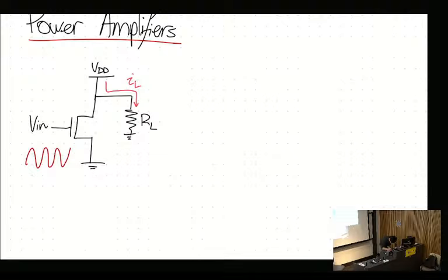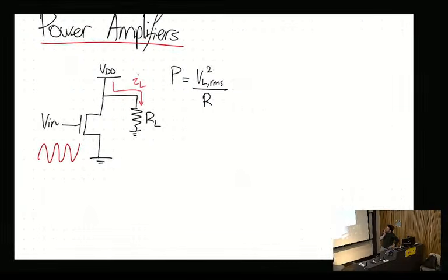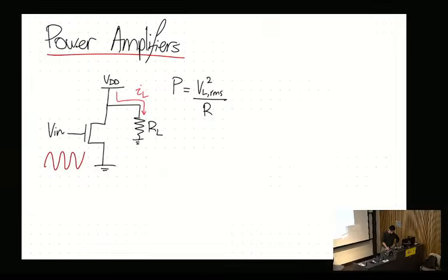And then the power at the amplifier is just V load RMS squared on R. So, just the standard power relation, V squared on R. Then there's the question of how we actually operate this as a power amplifier in terms of the different classes of operation. I always like to think of it, and I gave the exact same analogy last year, in terms of a tap and running water. So if I just draw for now, let me just move this.